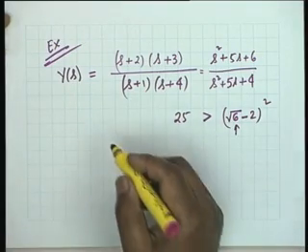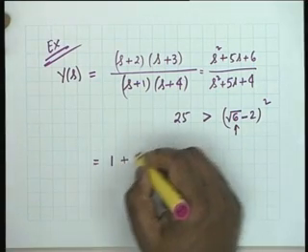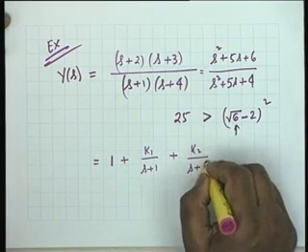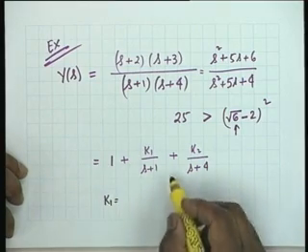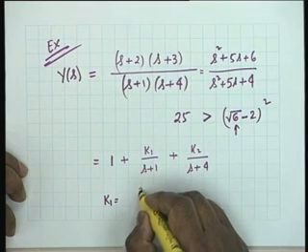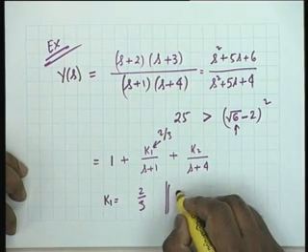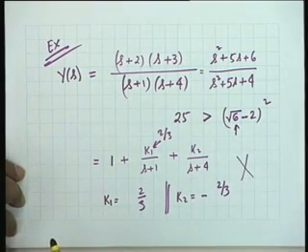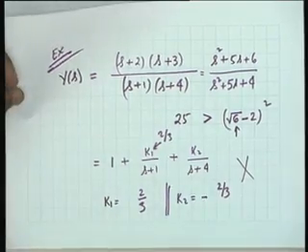Well, in partial fraction you take the infinite frequency value, which is 1, plus, let us say, K1 divided by s plus 1, plus K2 divided by s plus 4. Let us try. Does this work? K1: multiply by s plus 1 and put s equal to minus 1, you get 2 by 3. That is positive, good. Then K2 is minus 2 by 3. So this does not work. If it is negative, obviously we don't know how to do it. Okay, so we give up.